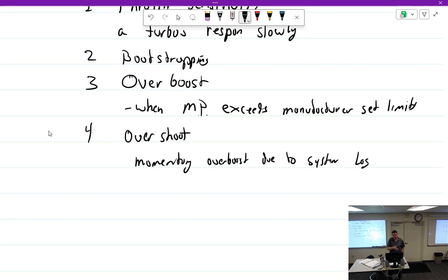So same thing with an overboost. You're running it for a little while in that position. An overshoot, I can get an overshoot with my RPM because the oil's cold in the prop, so I give it full throttle going down the runway. You'll hear props go past you, you can hear the RPM go up and then right back down. So it overshot but came right back in. Follow? So that'd be an overshoot. It hits a number but falls right back in line. Just watch it happen. That's not an overboost. So an overboost is going to be defined as something that kind of stays there for a while.